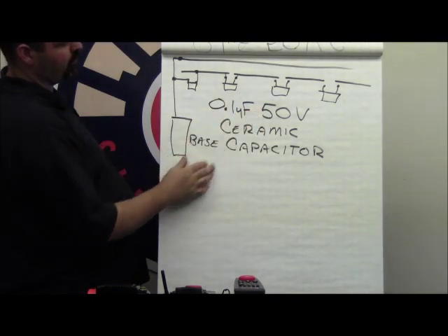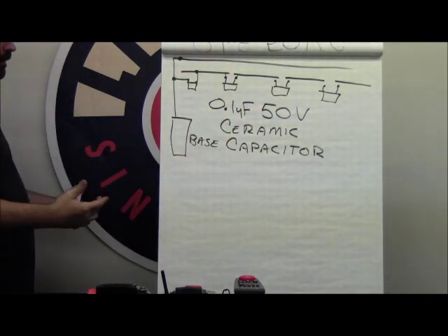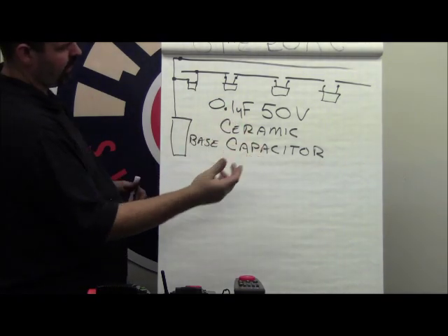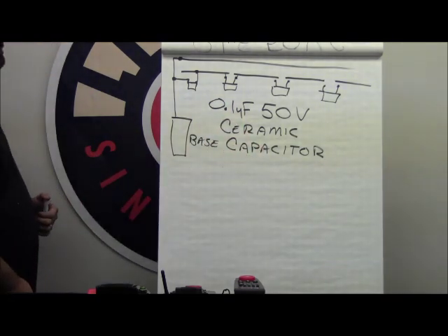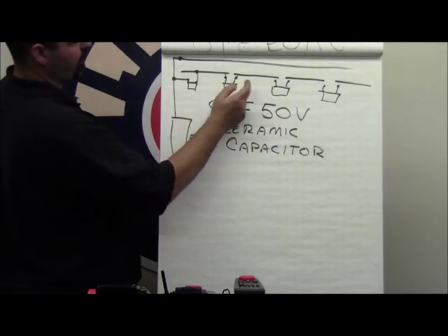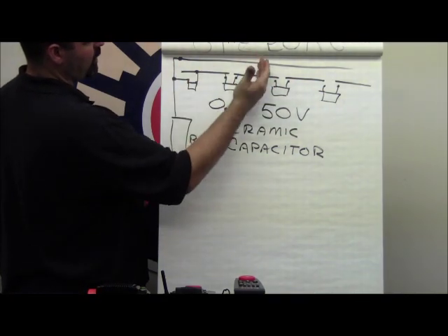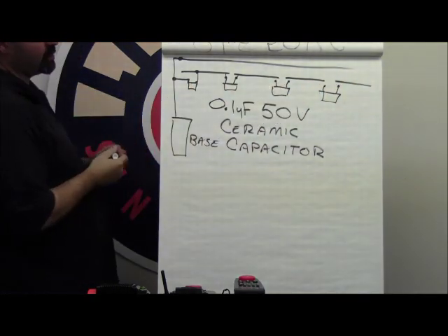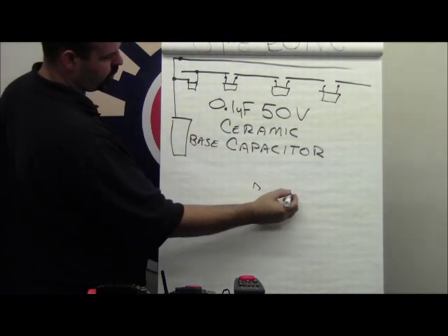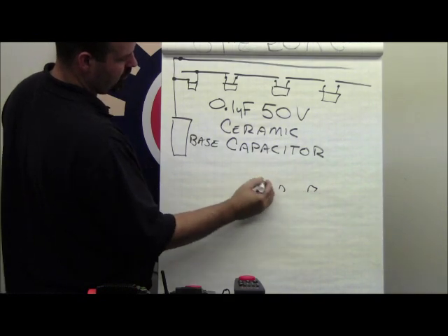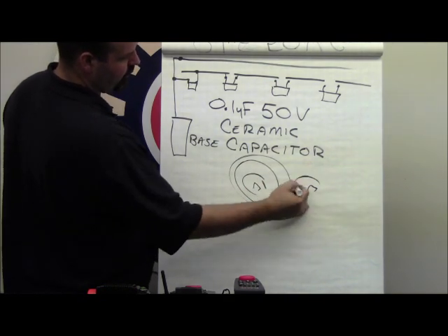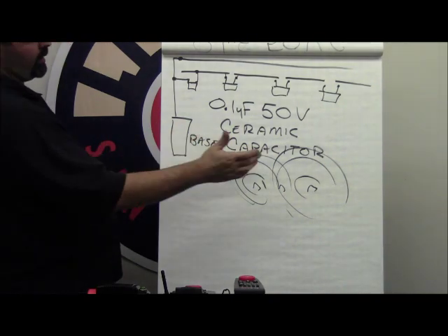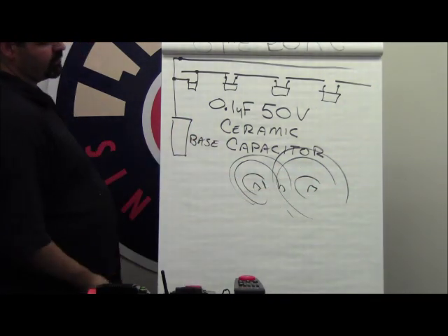These are very inexpensive components available from large electronic suppliers. A search on the internet, I'm sure, will turn up suppliers near you. But this is all that's required to get your command signal to broadcast from this insulated outside rail so that you still achieve the functionality of having both rails broadcast your command signal and still take advantage of all of your insulated outside rail detection functionality.